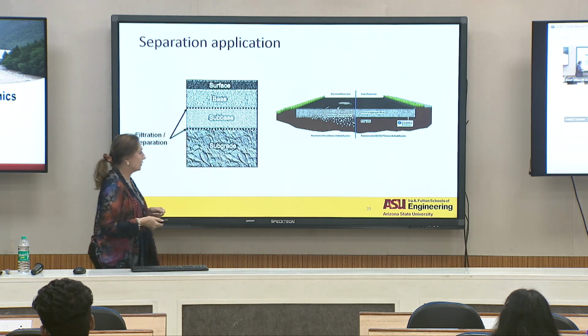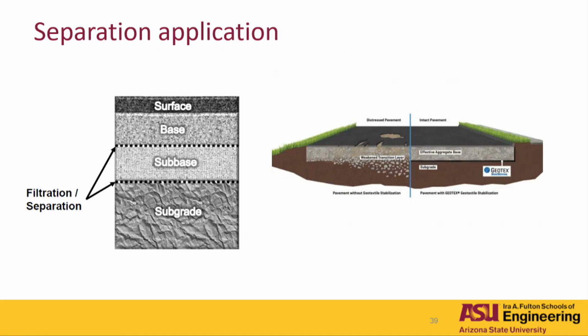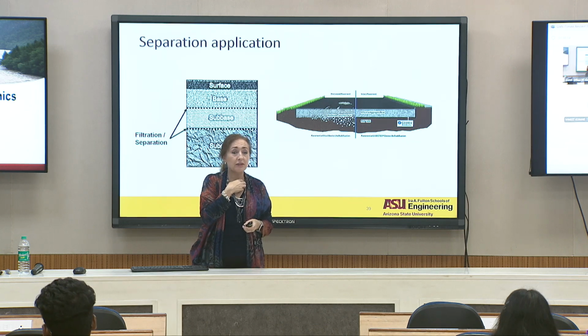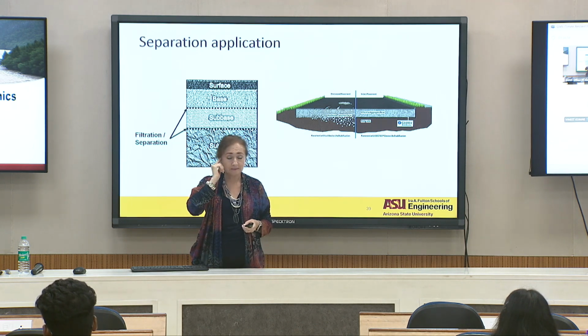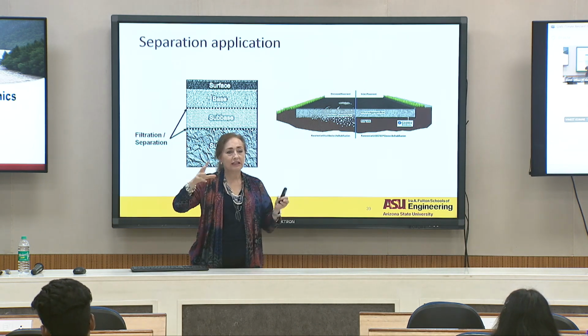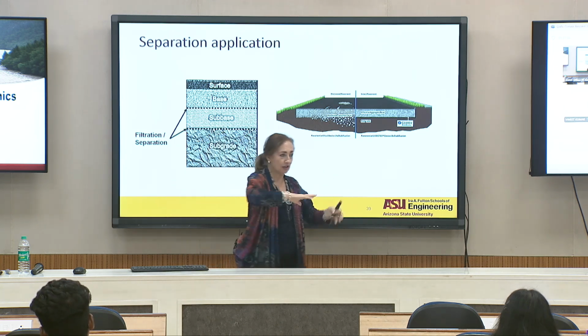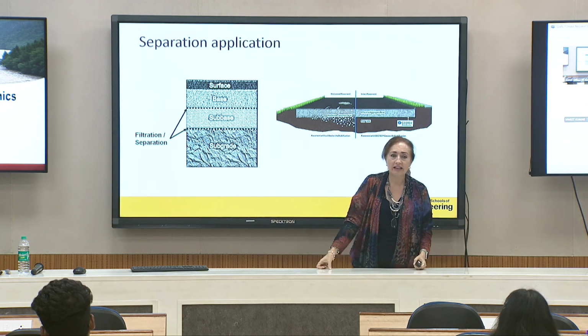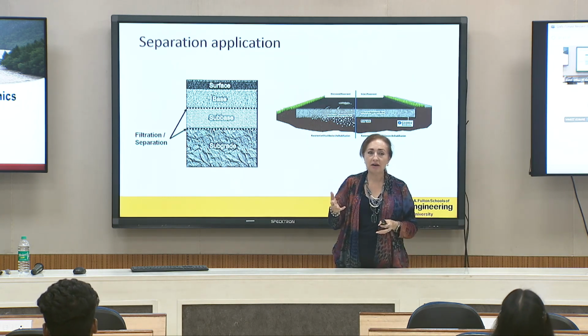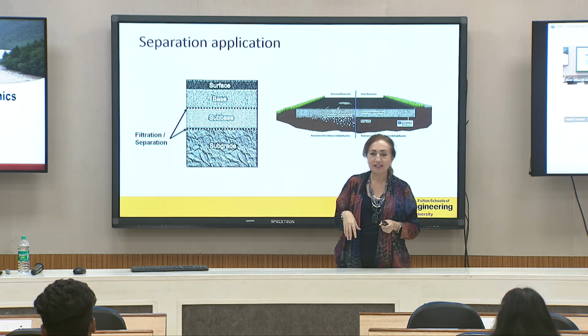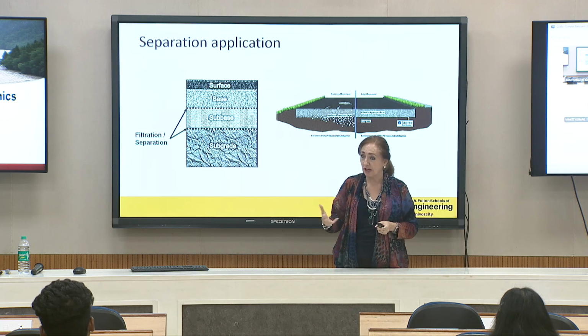This is important. The granular-based material cannot have more than 10-12% of fines, and some specifications are stricter than that. They should not have more than 8% to 10% of fines. The problem is when that granular material is sold to the state to build the roads, they sell it without washing it. It looks good, but if you wash it, you can see that the material has about 16% fines, because when they check it, they don't wash it.